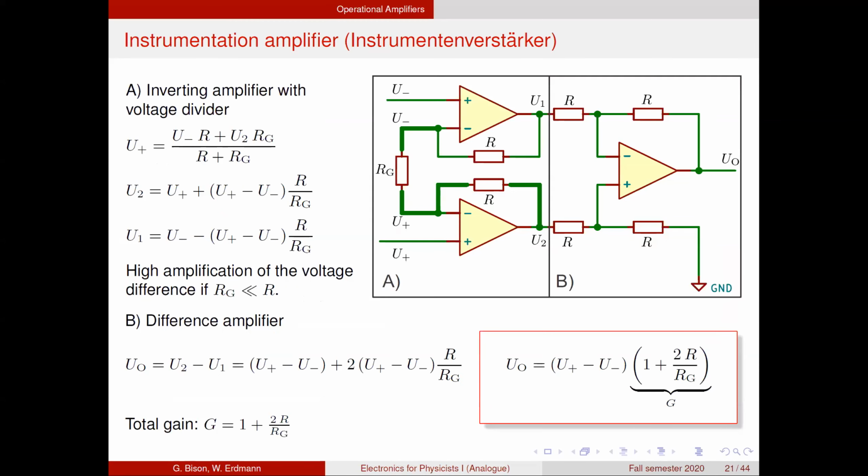Okay, so let's have a look at how this circuit works. And well, I must admit, this is not the most obvious op-amp circuit if you look at it the first time. So let's divide this into 2 sections. And how do you do that? It's always a good idea to divide at the output of amplifiers, because what comes afterwards does actually not change the value of this output.